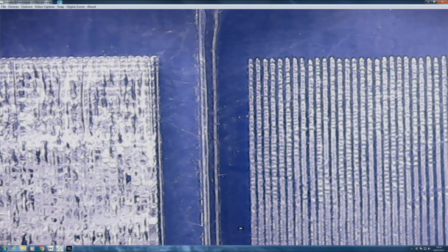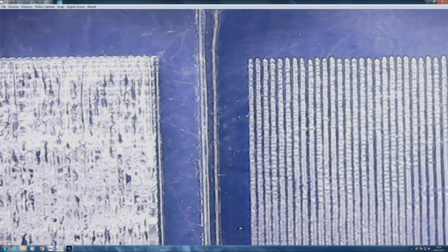This is a grayscale system where, I reinforce again, every pixel should have its own power value. Now, I specifically did not choose the spacing between these scan lines to be anything special. Technically, I should have chosen the spacing to be that suitable for 100 pixels per inch. I did not. I chose 0.25, which is probably not even an interval or a multiple of the correct line spacing. So there is a risk that what we're going to see in these patterns is an aliasing effect, where we get some of the dots showing and some of the dots not showing.